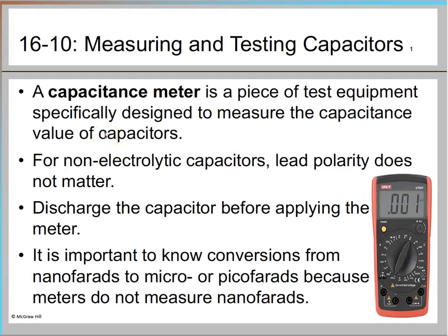To measure a capacitor, we use a capacitor meter, which is specifically designed to measure the capacitance value. If you're using a non-electrolytic capacitor, then the polarity of the leads does not matter when connecting to the capacitor meter. But if you're using the electrolytic type capacitor, then you need to see the polarity of the leads. And you also need to make sure that you discharge the capacitor before you connect the leads